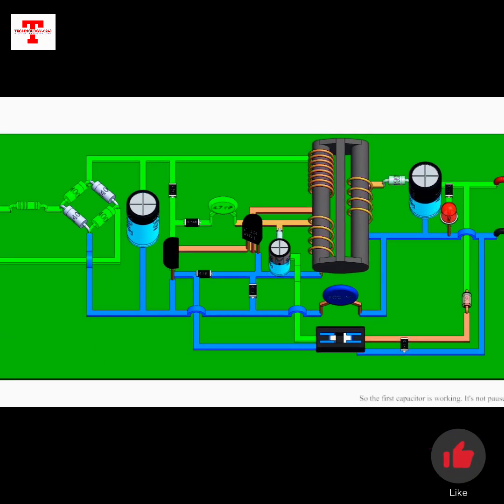Now you would have the question, why not directly convert AC to DC rather than this? This is because, for the normal power supply, which is at 50 Hz, the sizes of the transformer and the capacitors are large. They cannot be mounted in a small charger like this. Hence, in the charger the 50 Hz frequency is converted to 50 kHz. This reduces the size of the transformer and capacitor required in the circuit. So to change the frequency of AC, first we have to convert it to DC and then again back to AC.